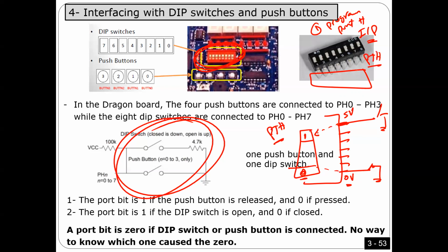You have this byte. You can just check the bit. That's it. We did that all the time, many times, in chapter 2. If you have a byte, how can you check some bits? If the bit is 0, that means the switch is connected, right? If the bit is 1, that means the switch is open. And then after you know if the switch is connected or not, you can do something.